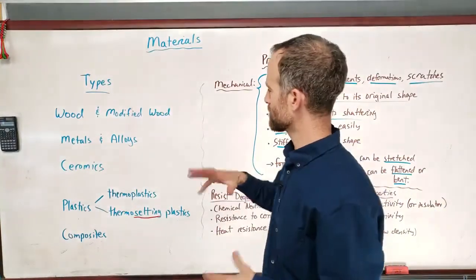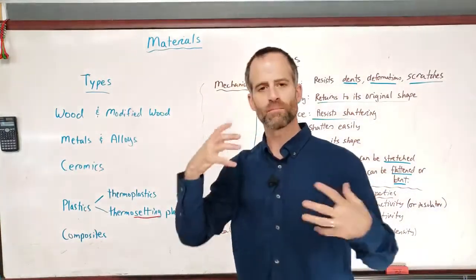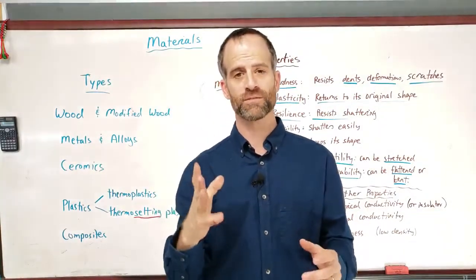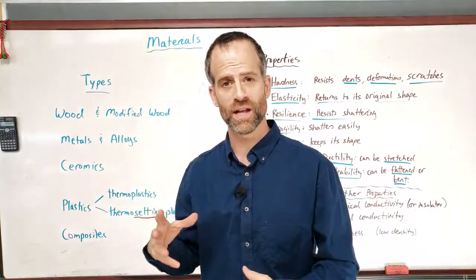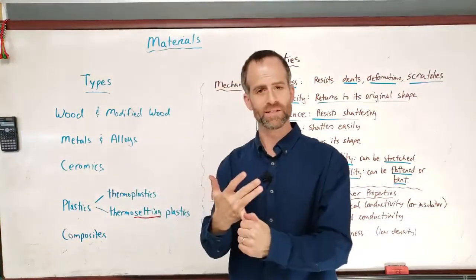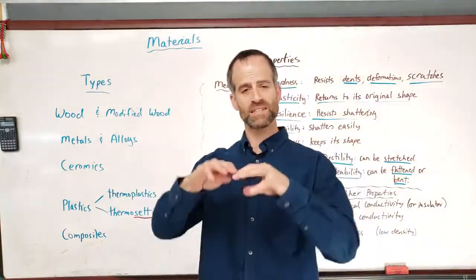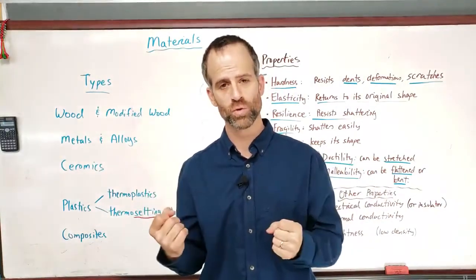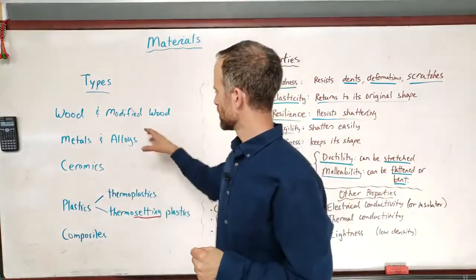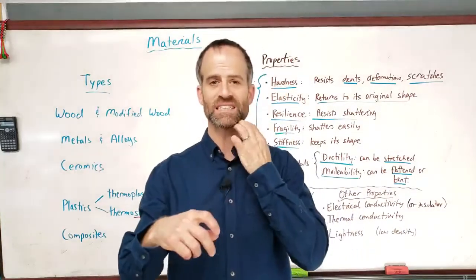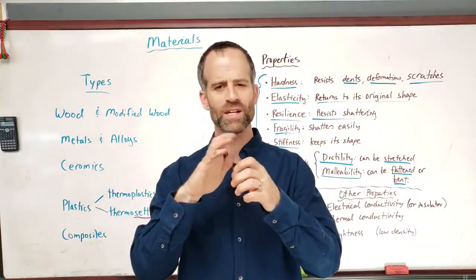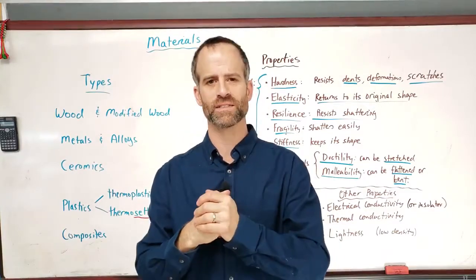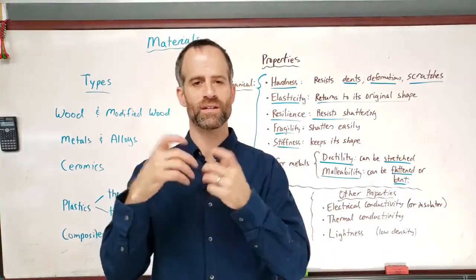Okay, quick thing about metals. So how can we modify the properties of metals? Well, there's first of all resistance to degradation. We might coat it with a paint. We might galvanize it, which is basically coating it with a metal that doesn't rust, doesn't corrode. So you may have seen some bolts for decks and stuff. They have sort of a grayish type metal over it. It's kind of rough. Those have been galvanized. They've been coated with another metal that doesn't rust.